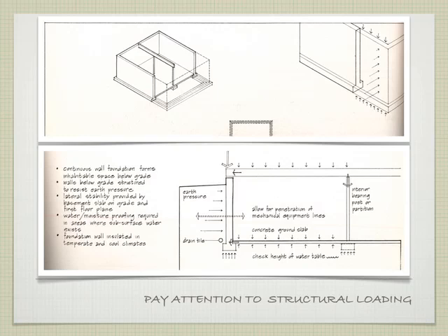But in the case of a basement, we have a hole on this side, we have dirt on this side, and we have pressure causing lateral force on this wall. So just like we talked about with the excavations, we have to deal with how we support that kind of pressure on the wall. It depends on how deep the basement is, and there's a variety of strategies. But it's important to recognize those types of loading on the building.